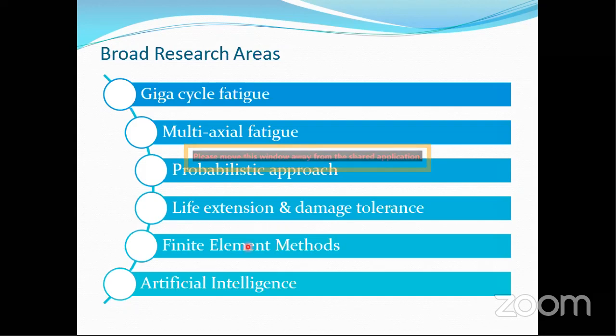And coming to the finite element methods, because of stress singularity at the crack, it is very difficult to mesh the crack at that location. It is not only because of stress singularity, it is because of the geometry of the crack. A very fine crack tip has to be defined, and to capture the crack propagation, the mesh has to flow with a very fine mesh.